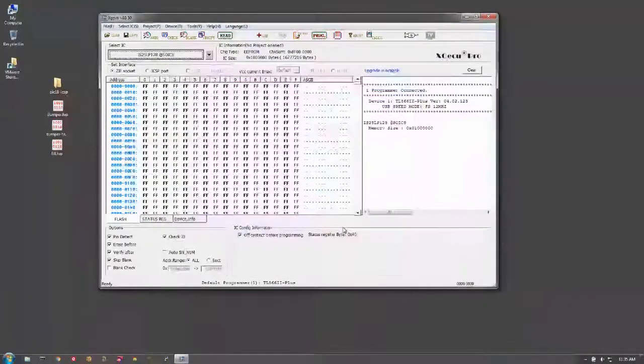The way that I knew the chip is I looked on the circuit board and I could see the part markings on the chip, and it tells me what it is. Or if you had a schematic, or maybe you would have to work that out by some educated guessing, saying, oh, it looks like a memory device, but there's no part numbers on there. I'll give it a try and see if I can automatically identify the correct pins. So we've chosen the correct thing here.